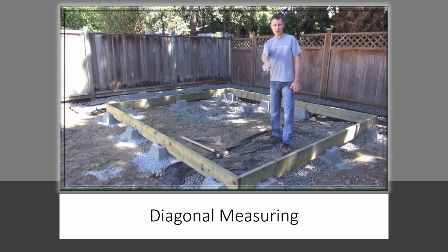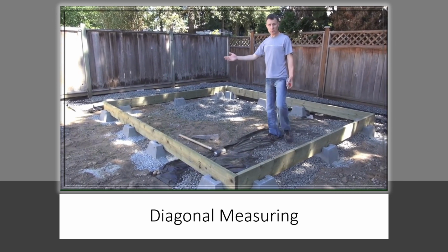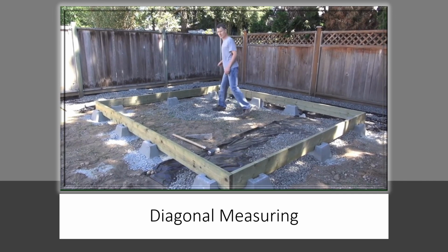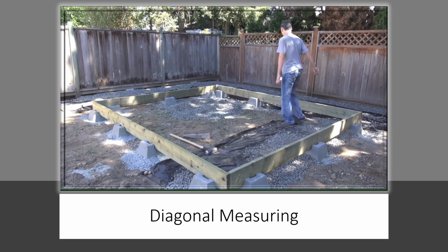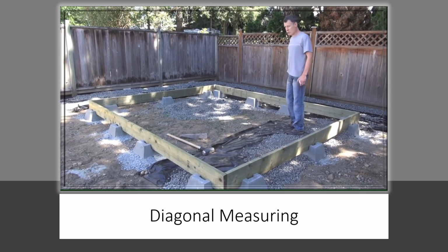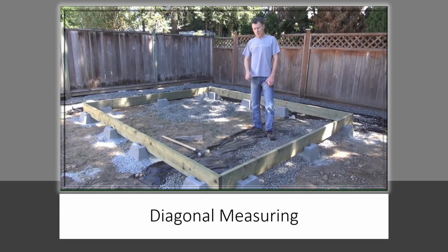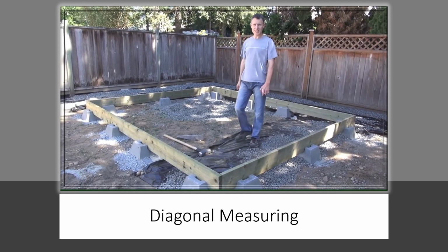Those need to be right angles. They all need to be exactly 90. Now one way of course you could check it is using the Pythagorean theorem. You could measure that side, you could measure that side, and then you know how long the diagonal is, doing some calculations. But since it's a rectangle, there's actually an easier way to do it.